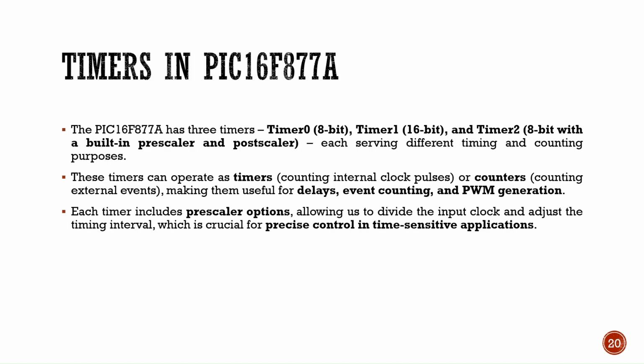Timers in PIC16F877A microcontroller. The PIC16F877A has three timers: timer 0, 8-bit, timer 1, 16-bit, and timer 2, 8-bit with a built-in prescaler and postscaler, each serving different timing and counting purposes.